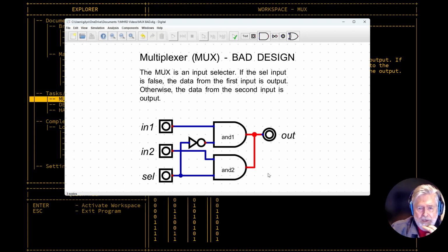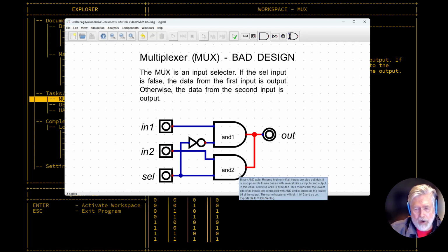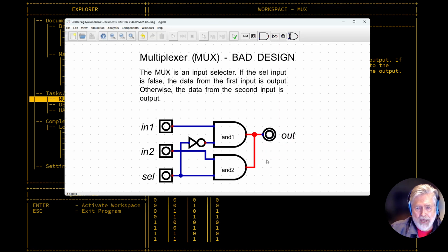If this wire was grounded with a high impedance resistor, then the circuit here would basically work, because even though one of the values is at 0, assuming that value is at ground, putting a high voltage value on the wire would not hurt anything, because you have a high impedance there, and it would just generate a voltage across that impedance with the high value, and the output would get out.